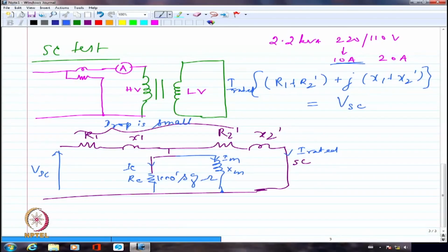Okay? So this VSC that I apply is normally done through an auto transformer. So I'm going to show the auto transformer here, and this is applied by influencing the voltage with respect to only a fraction of the total turns available in the total auto transformer winding. So this is where I apply the 220 volts or 230 volts. So I'm going to apply V rated probably at this point. Rated voltage is applied here.